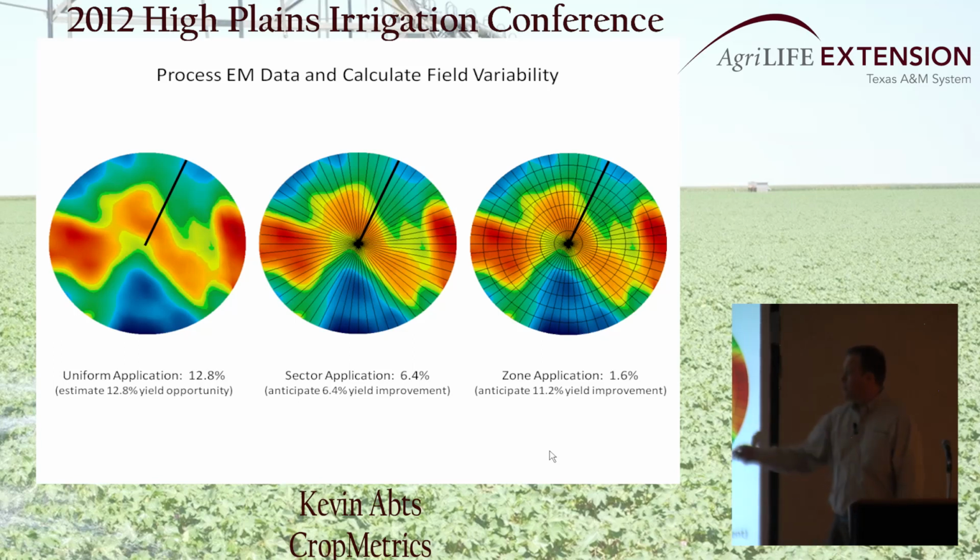So I would say for this field, there's an opportunity for any of these two. Again, with this one, you have a pivot track GPS, you're ready to go. Very reliable. Again, we're not changing flows and pressures. And it's very easy to tell that you're managing to this degree. This requires a little bit more equipment. It does require the Valley Pro 2 computer main panel, a series of control boxes, and a series of Aquamatic valves to be able to, again, bank these sets of sprinklers and cycle the rates.